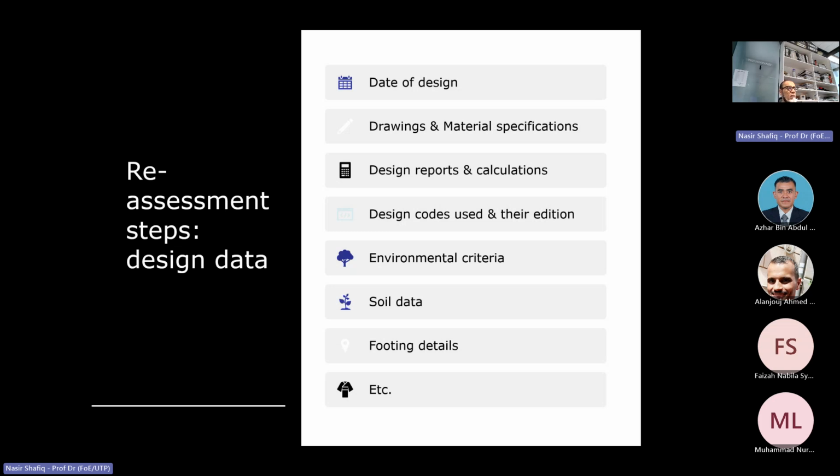So the properties of the soil where your asset is situated are important, and foundation or footing details, etc. So these are the information, data or reports you have to have access to for the reassessment of the integrity of your structure.